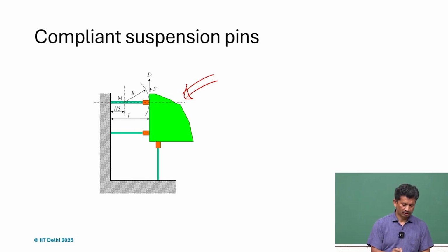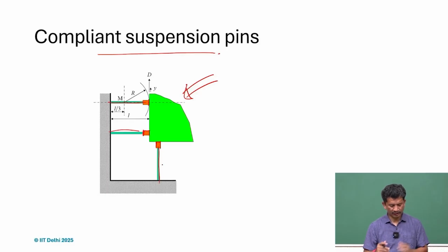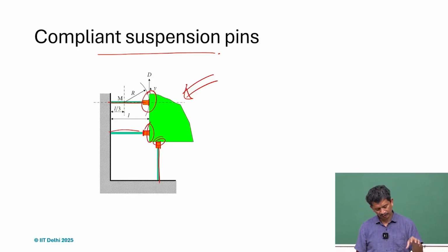Instead of the solid supports, we can also use compliant pins, so that we don't have any slip here, and any deformation will be in the compliant mechanism.